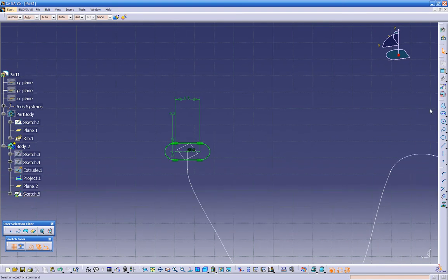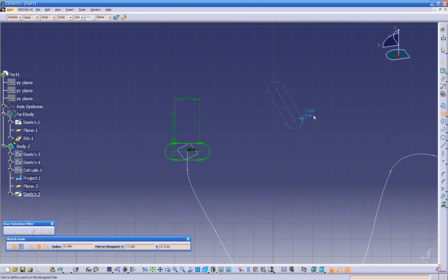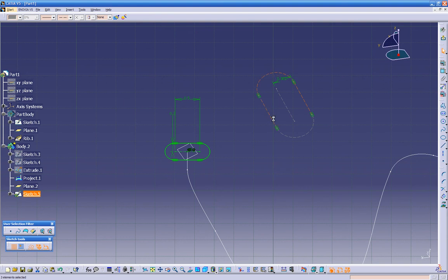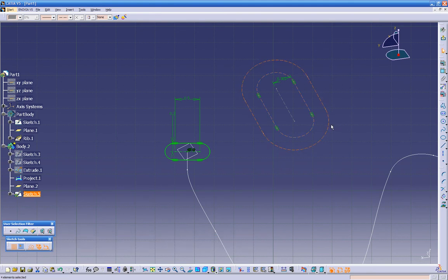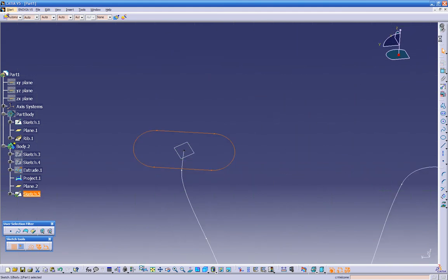What I was going to show you over here by this offset, if we have this, we can just highlight the stuff that you want to offset. Just click on this option right here, and you can go bigger or smaller. Or if you hit the tab key, you come down here and make it 0.300 and click OK, and that's our dimension right there. So that's offset, but we don't need this anymore. So let's get out of here.